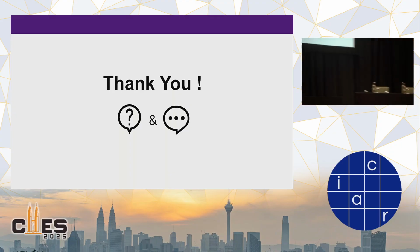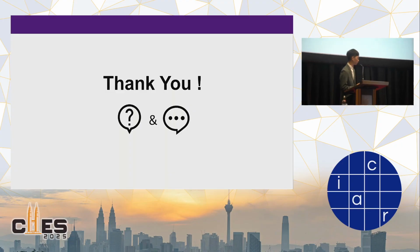In fact, the time over which the correlation accumulates is changed by the design parameters, like the PLL's bandwidth, the frequency of the PLL, and maybe the PLL's divider factor. So it's not typically an exact value of how much time is accumulated, and we can not ignore the correlation. It's specific to the design parameters.